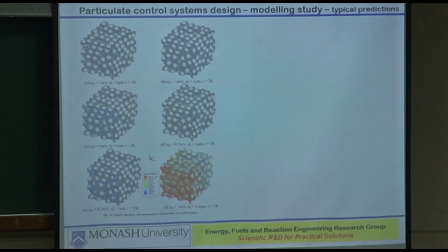That will affect my purging sequence. How much gas I will purge, at what frequency I will purge with nitrogen to clean up everything that has been deposited on these filters, first row, second row, third row, etc. Okay.